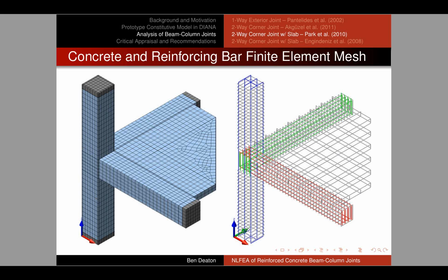And you can certainly start to see the complexity of the reinforcing bars. But these are very easy to simulate in Diana. I would make one copy of each of these and then copy it in each direction to fill out the reinforcing. This type of model can be generated fairly quickly with FX+. Again, you can see that we have anchored beam bars in the joint core, but there's a complete lack of any transverse reinforcement in that region.